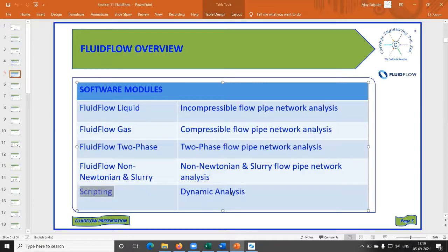So if you have, say, a cooling water supply system, this network simulation is to be done. Can you use HYSYS for that? The system is, your cooling water tank is there, then cooling water supply pumps, and that header goes to different heat exchangers all over the plant, right?